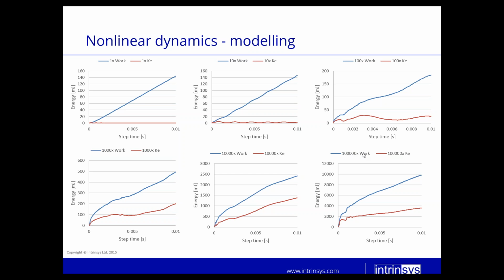Now if it's skewed and distorted, even if it can be, let's say, 10 microns wide, then that would decrease your time increment, maybe E minus 9, E minus 10. So if you have a very large model and you want to solve it in reasonable time, maybe it is required.